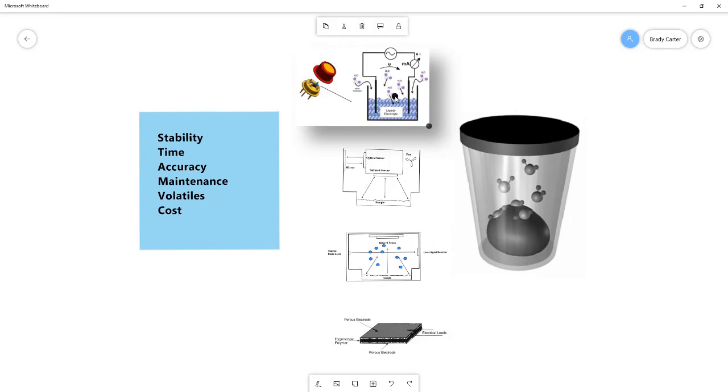The electrolytic sensor measures it by tracking changes in the resistivity of an electrolyte solution as humidity changes. Similarly, the capacitance sensor measures the changes in electrical properties of a hygroscopic polymer due to exposure to different humidity conditions.